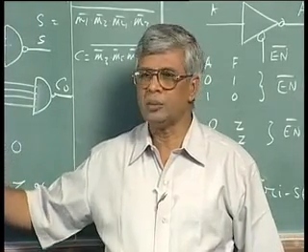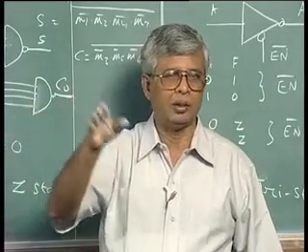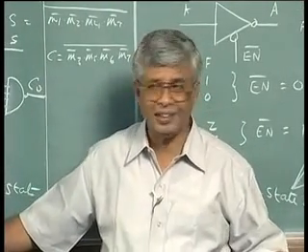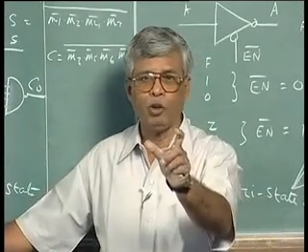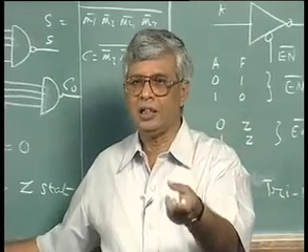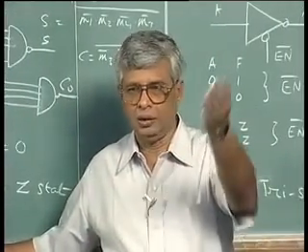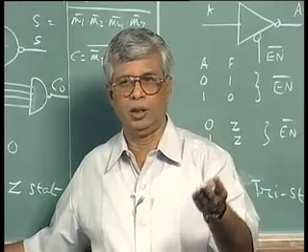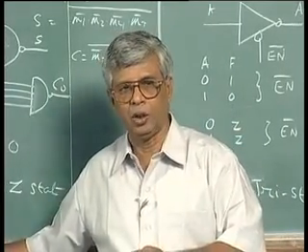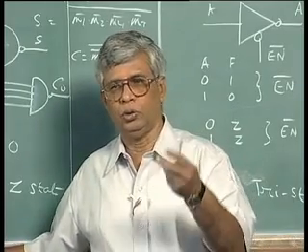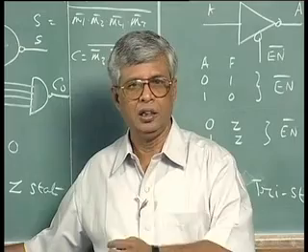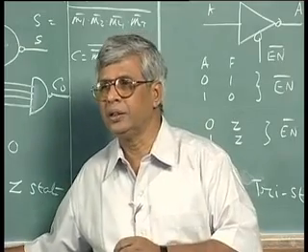These are combinational logic building blocks, multiplexers and decoders. But if you think of a counter, a 4-bit full adder is an MSI, right? If I can make one 4-bit full adder in one IC, each full adder, you know about how many gates? There are 2 exclusive OR gates for add, and 4 gates for the carry and all that. If you add this, something like 24, 25 gates. It qualifies for an MSI.